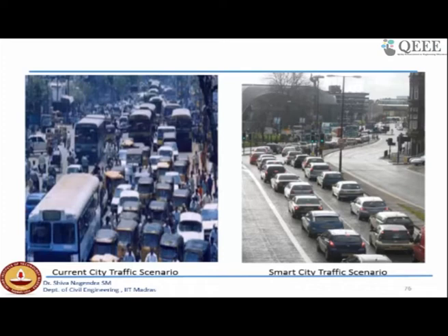Now you want to reduce, at this level, by 100. So how do you control 100? You need to understand what the meteorological conditions are that are dispersing the emissions contributed by this. What is the worst case scenario? Whether you achieved 200 microgram per meter cube, does it correspond to the worst case scenario, or is it on a normal day? Then your model will be able to help you quantify the highest concentration you can predict corresponding to this situation.